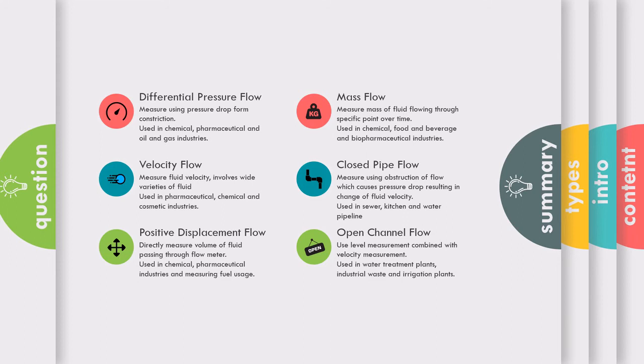Poorly selected devices invariably will cause problems at an early date, as each flow meter has its own specific application and installation constraints, so it is wiser to use the application as the guide to choose the right flow meter rather than the technology required.